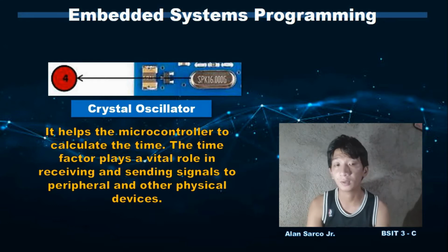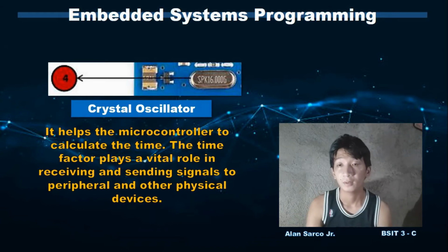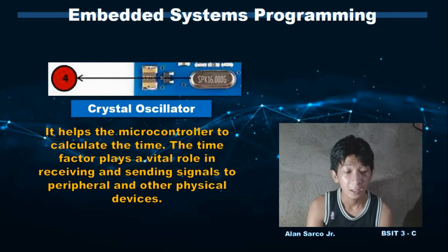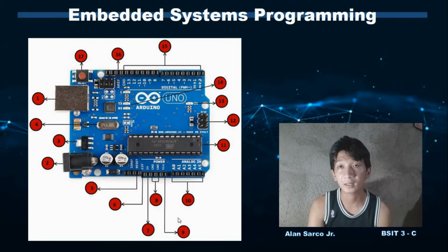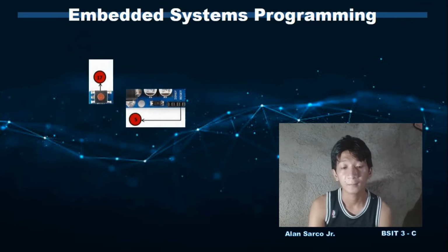The crystal oscillator is important because it provides the clock to the microcontroller. And in our microcontroller or microprocessor, all instructions are executed in synchronization with the time. So if it breaks or we remove it, there won't be any kind of machine cycle generated in our microcontroller and the instruction won't be executed. So that is the use of the crystal oscillator.